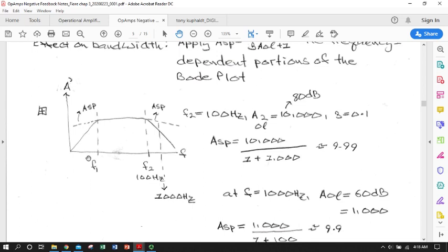That onset is marked by what's called a critical frequency, at which we have half the gain power equivalent that we do in the midband, and that's your F1 or F critical 1. You move through the midband, and in here you've got a flat line, so your gain is the same regardless of frequency. This is the midband.